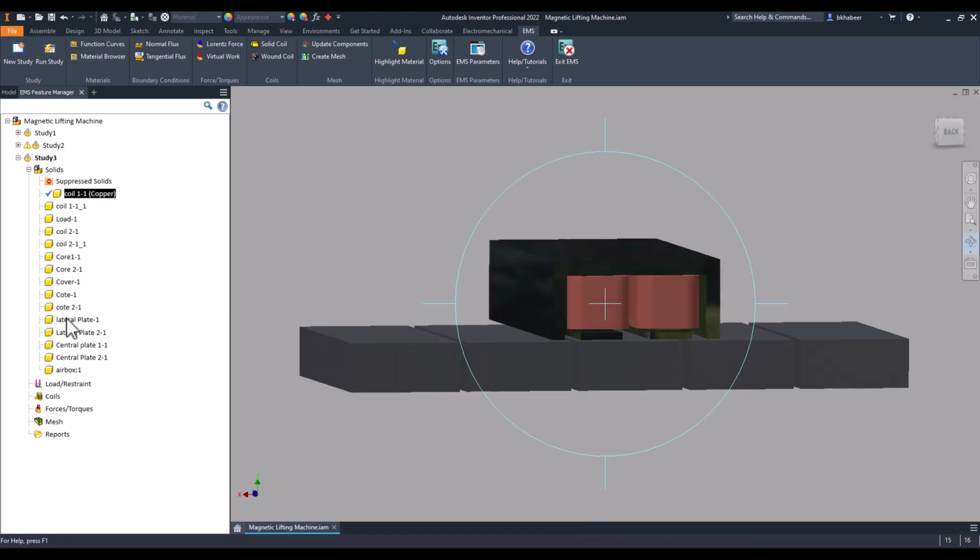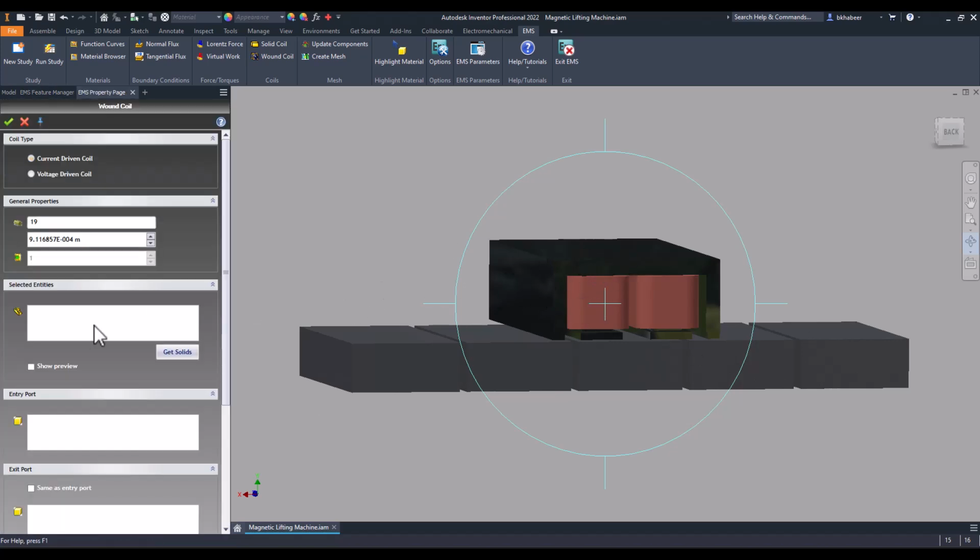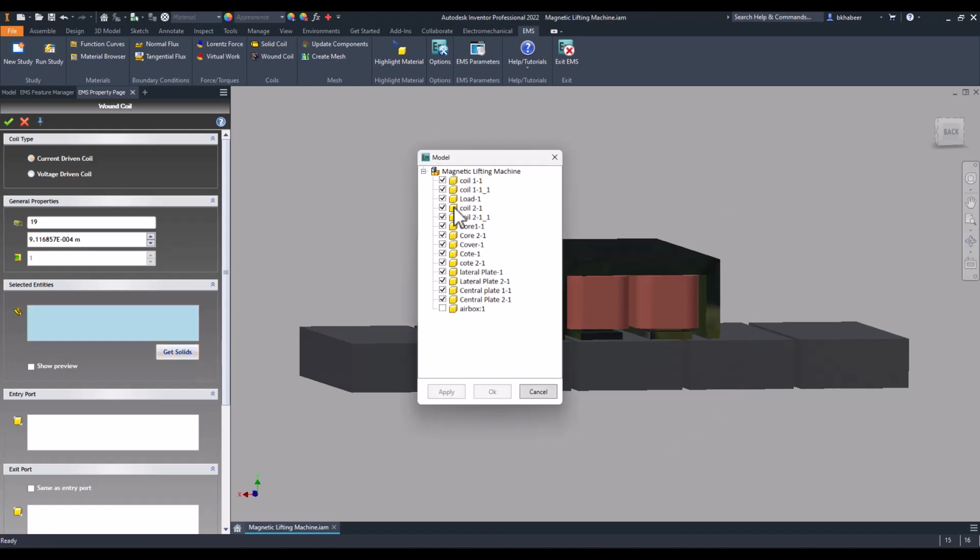You do the same for other materials. You can do multi-selection to save time. You can apply from favorite or recently applied materials. I can apply from this menu. Then once you apply all the materials, you go and apply the excitation. Basically there are coil options, so you can apply your excitation. I want to define, for example, a stranded coil. A solid coil is for conductors or geometrically modeled coils, but for these kinds of equivalent coils we can use this option of stranded or wound coil.